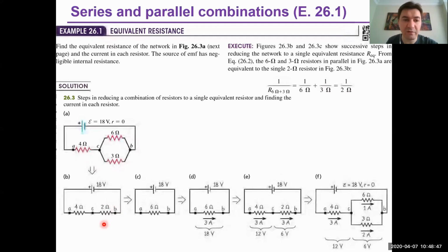That part is 2 ohm, okay? We have here 4 ohm. In total, we have 6 ohm. This is the equivalent resistance of the complete system. So we have 18 volt, which is coming from the EMF, right? And we have 6 ohm here. So what is the current? Current can be calculated. Current passing through within that circuit from positive to negative is given by 3 amp.